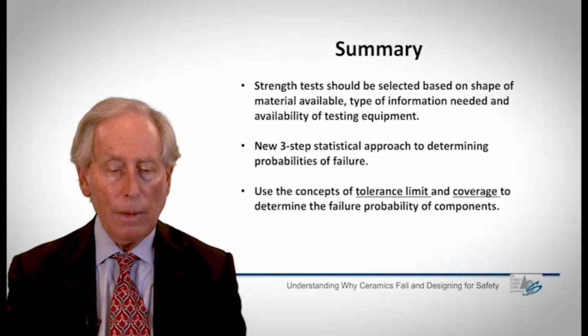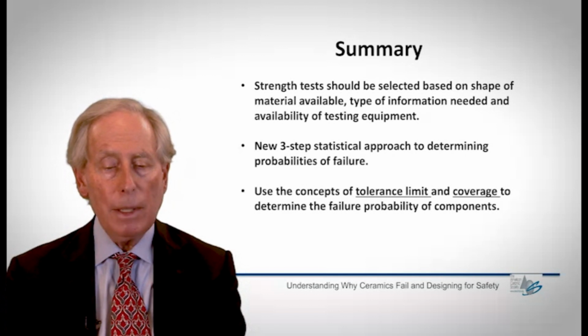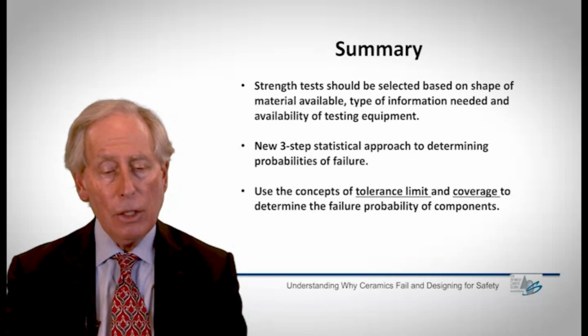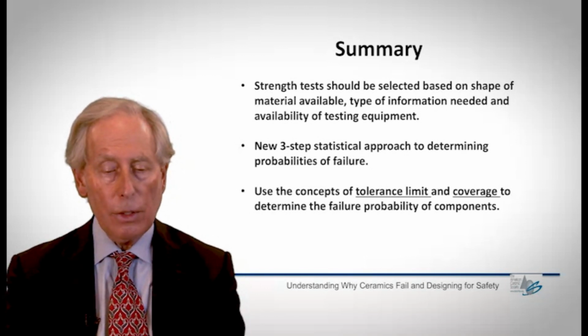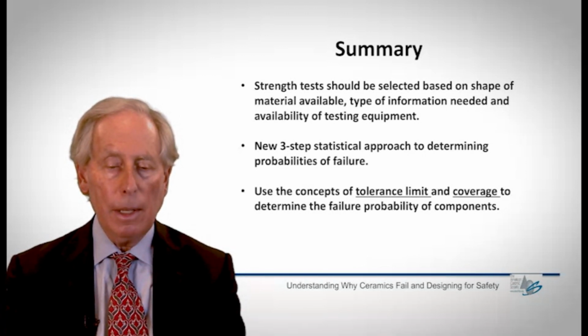So let me just summarize briefly that on the idea of strength measurements, that you select your strength measurement technique based on the shape of the material available and the type of information needed and the availability of testing equipment. It all seems very obvious, but it really helps in determining how you do the test and how good your data will be. We've tried to show that there's a new three-step statistical approach to determining probabilities of failure, and these use this concept of tolerance limit and coverage to determine failure probability, which is really what I want to know. I need to know the lowest limit of the stress or the strength of the component in that particular application.